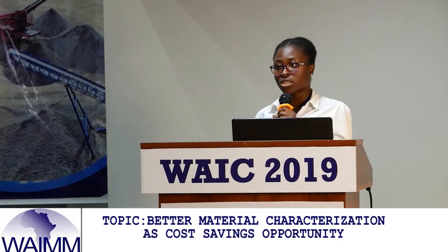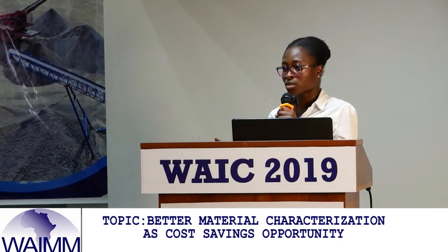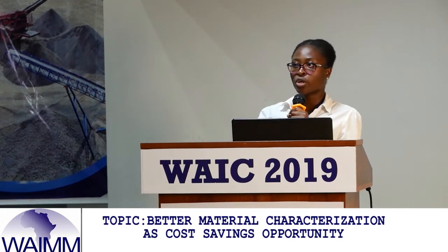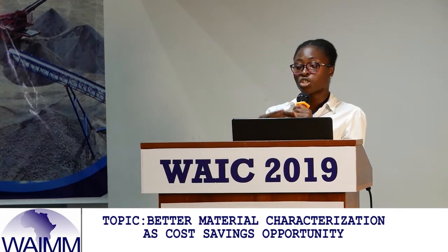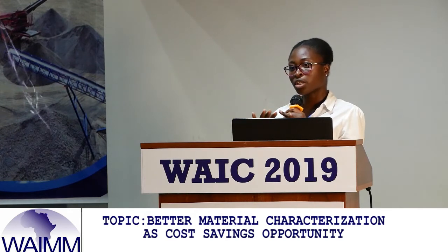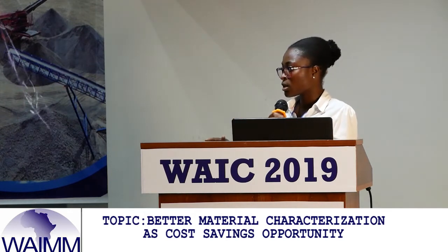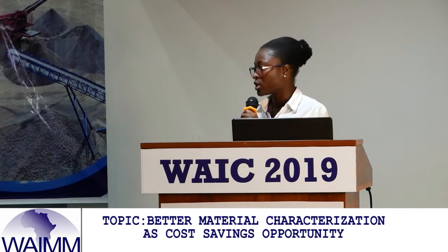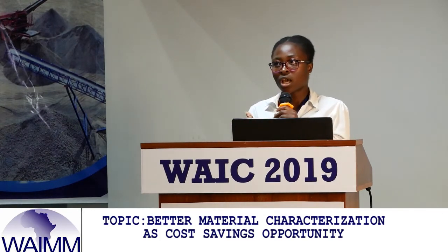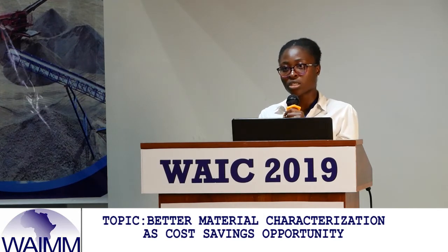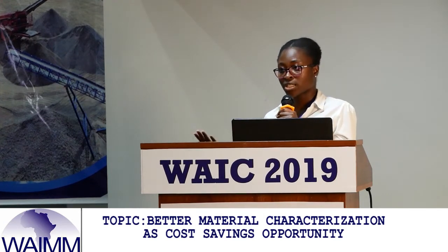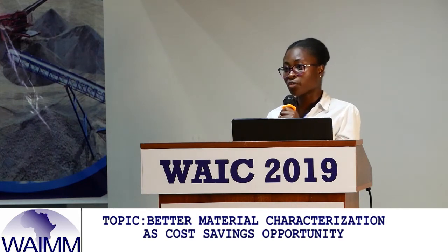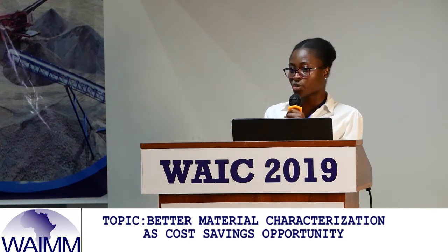An upstream raise means that we've built an embankment, we've built a TSF, we filled it with tailings, and we're going to raise the embankment by building part of it on the tailings. So we have a smaller footprint, which is good for sustainability. It means we are not affecting too much of the environment. But if we don't know that our tailings is stable, then we don't want to risk using it as a foundation for anything. So we'll do a downstream raise.